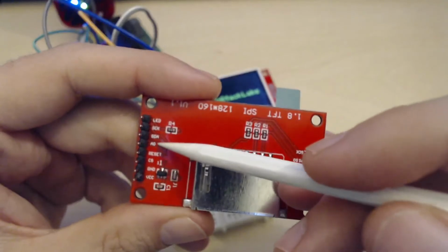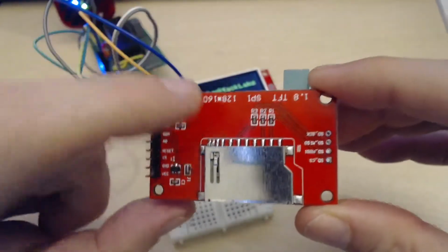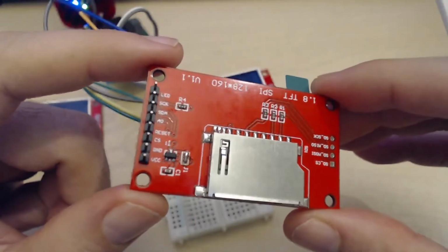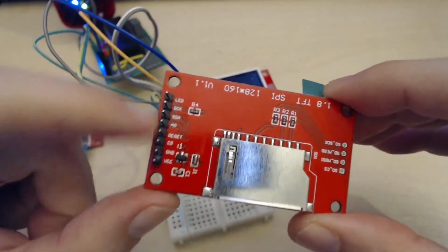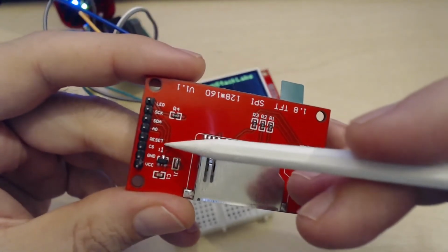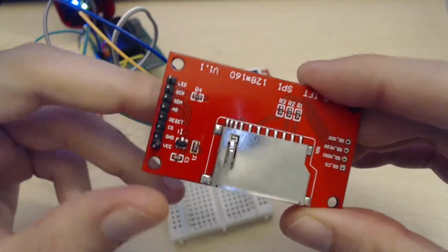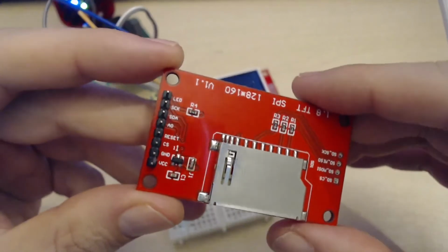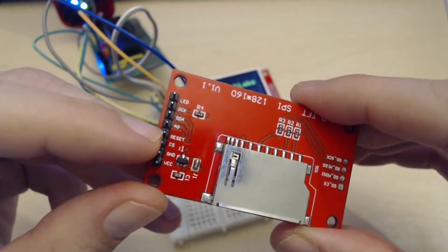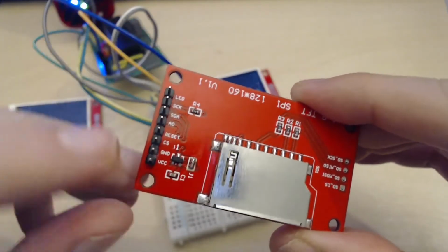So that's what it is for. And this data command pin is for when you write bytes to it, you have to tell the chipset, the driver inside the module, whether you are writing a command or data. It needs to know about that. And what else? We have the reset. Obviously, you need to drive it high to keep the device in on mode. You can just hook it up to your microcontroller, or just drive it high with a resistor. That's all good. Talked about the chip select, and you have ground and VCC at the end, which is obviously